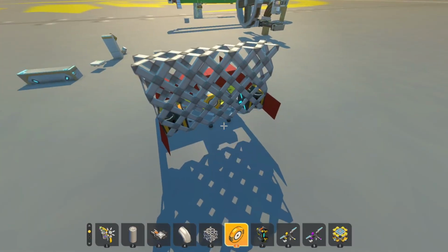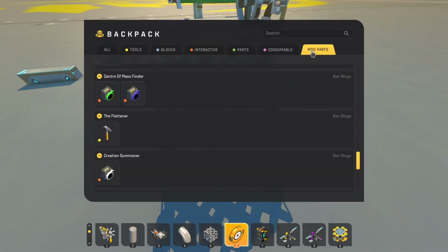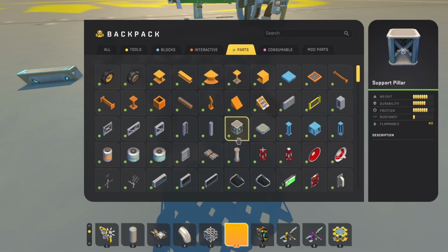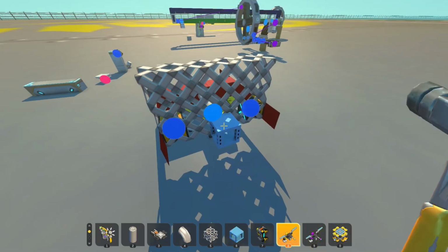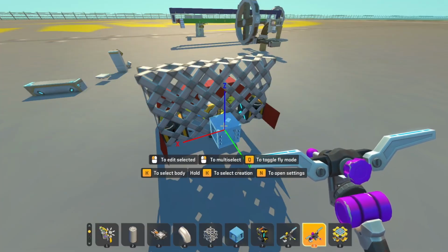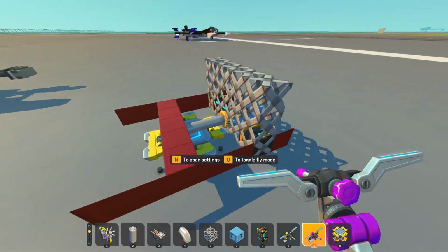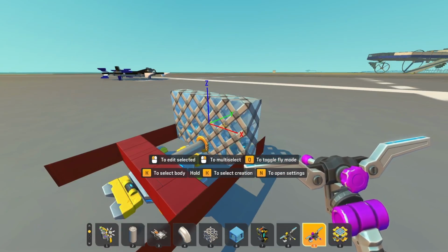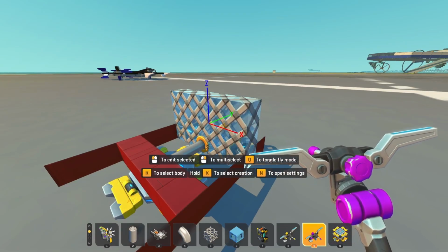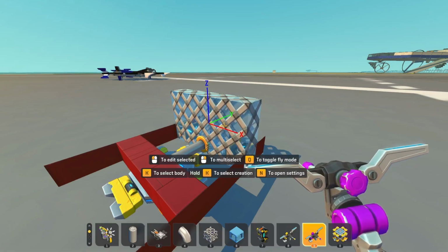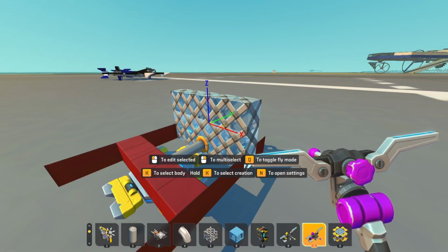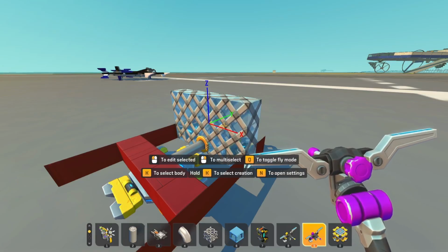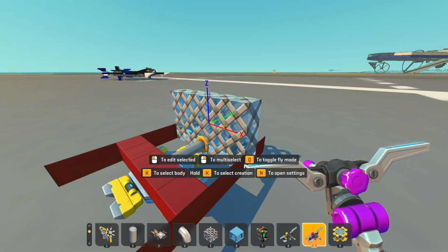Now, this is important. When you make a block a zero width, it needs to have some amount of mass on it, because for all intents and purposes, they don't have mass. Built into the SMTC tool pack is a safety feature that will delete any zeroth blocks that don't have any mass, because they can go fly off into the void and mess with the integer limit, and your game won't be very happy with that.